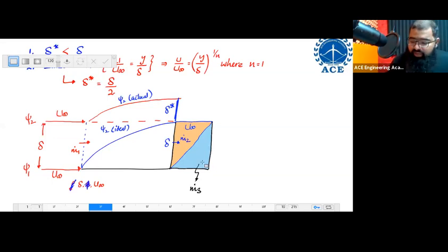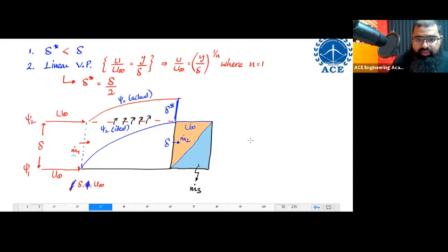Now, what should this mass flux be? You see, this mass flux is basically saying previously m dot 2 and m dot 3 combined were equal to m dot 1. Both of them were between these two streamlines. He is saying I was initially between these two streamlines, later also I should be between these two streamlines. So he is not accepting to be reduced. He is saying I will push this side upward so that he creates some vertical distance so that I am allowed to move.